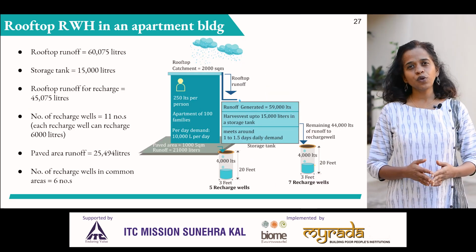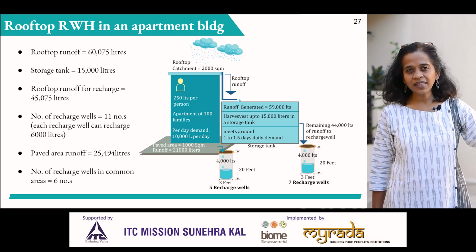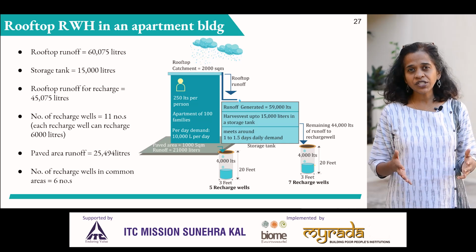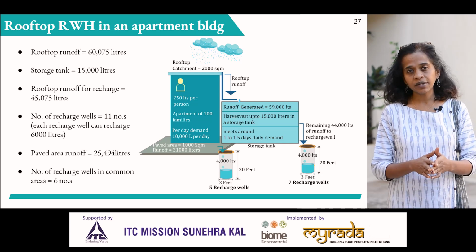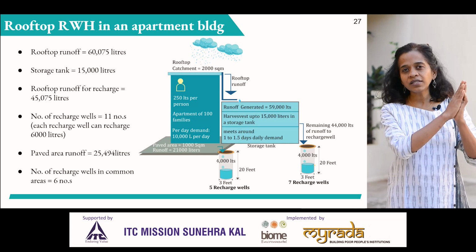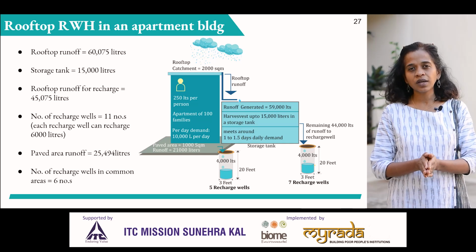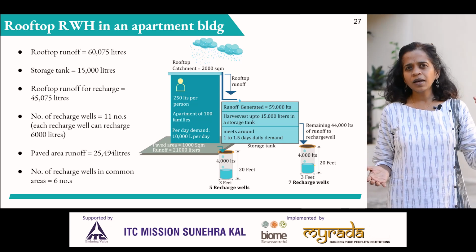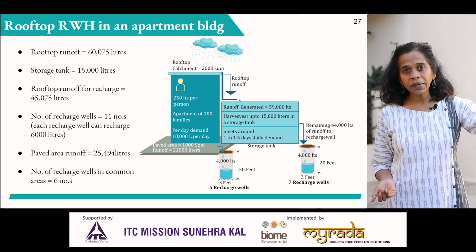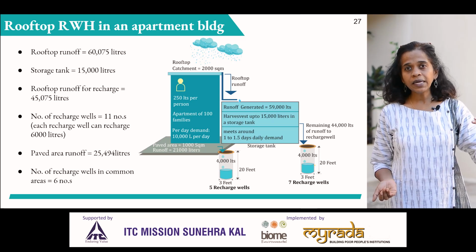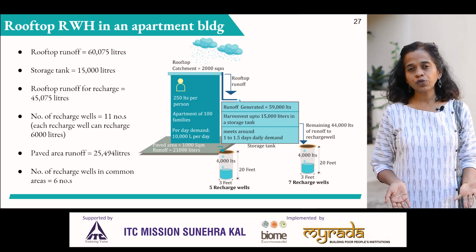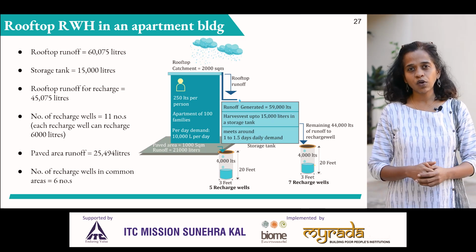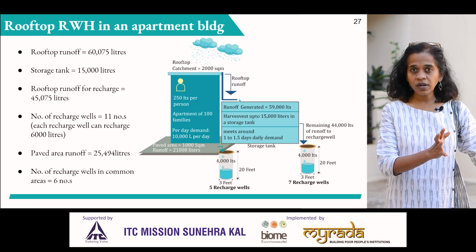If you look at rainfall, rainfall is measured for the rain that you receive over a period of 24 hours. So let's say an average rainfall in Bangalore is 30 millimeters, received over a period of 24 hours. When it falls on an apartment block that's located on 1 acre of land, perhaps the rooftop is about 2000 square meters of rooftop, for a 30 millimeter rainfall over the period of 24 hours, we receive 60,000 liters of runoff. This water can be stored in a sump.